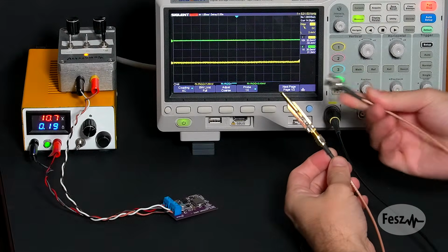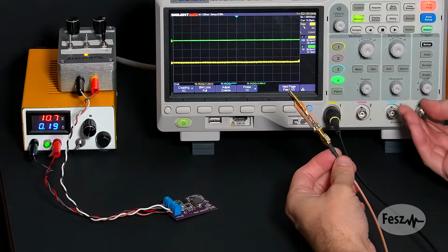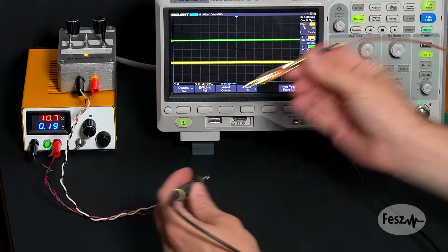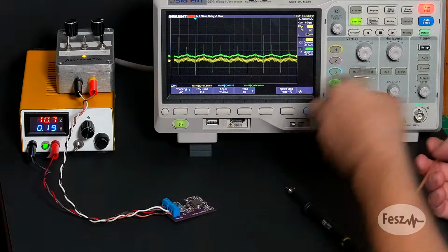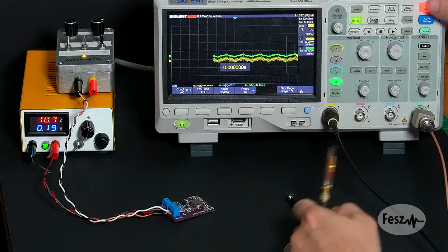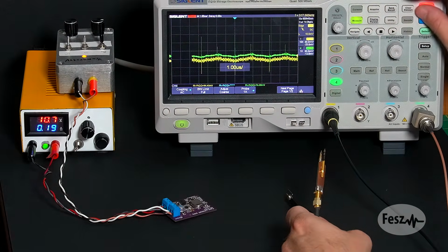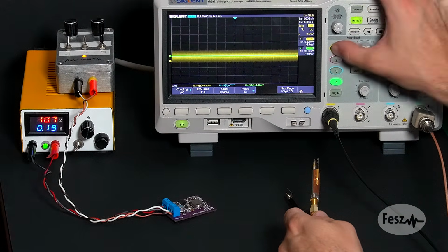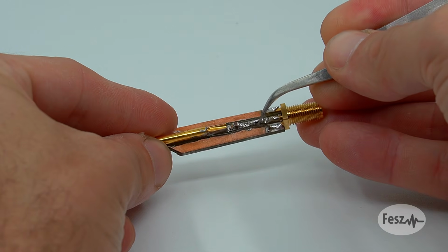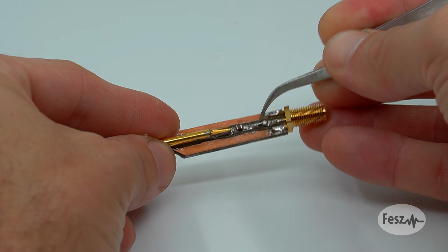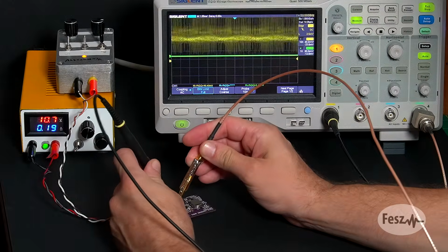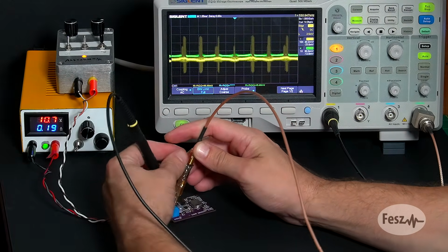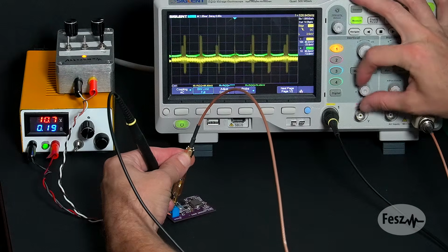To test this out, I performed two measurements, one in which I used the probe tip highlighted earlier and connected directly to the oscilloscope, and in the second set of measurements, I placed the inline termination at the oscilloscope side and just connected the 50 ohm transmission line through a capacitor to the test circuit. I used the same probe as before, just placed a short circuit over the 50 ohm resistor. In both cases, I also used the normal X10 probe to have a direct comparison of results.